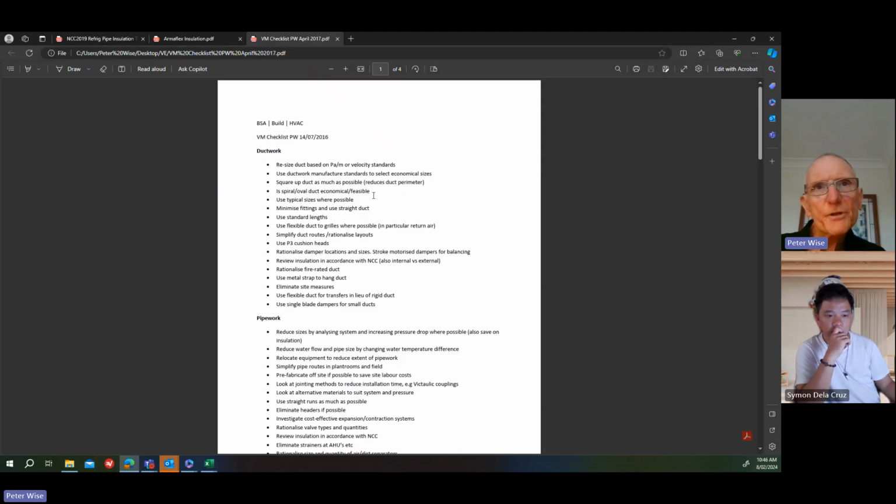I don't know whether you've been to a duct factory, but most of them these days are automated. So from your drawings, it'll go to a computer-aided manufacturing program, and then the machinery will start to make the duct. It's just automatic. So once they set it up for a certain size, say 250 by 250 or whatever it may be, it just punches it out. It just keeps coming out. And it's quicker for them to do it that way and then put it together than keep changing the program to make a different size duct, and change it again, and change it again.